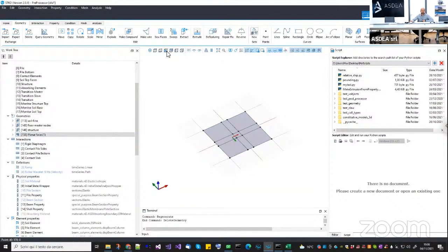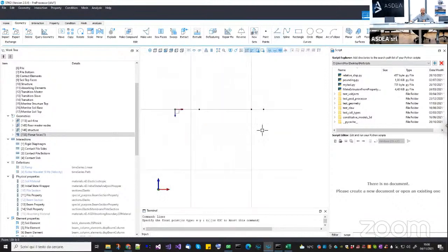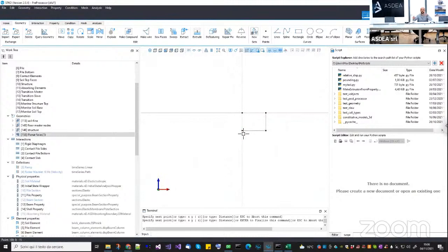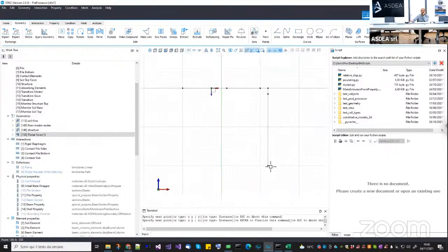Now I want to extrude it. By how much? Well, first I need 15 meters here, so I type 15, press enter, in such a way that I first do an extrusion of the first 15 meters to create the hole, okay, and then extrude the remaining, which is something like this, okay.